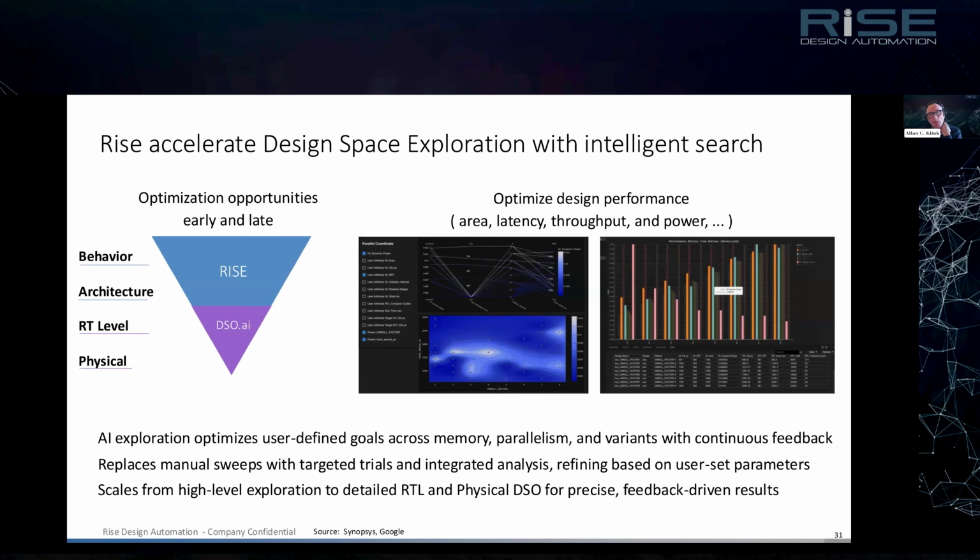As Mike outlined, one of the benefits of high-level design is that when you are in an untimed world, you have a tremendous amount of freedom to change the shape, to change the implementation of the design. Unlike what we are used to in RTL design flows, where we have to spend a tremendous amount of manual labor to reschedule a timed design, we can do that very easily in a high-level design flow. That becomes particularly interesting when you are working in a design space exploration mode.